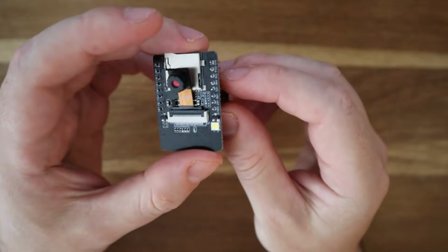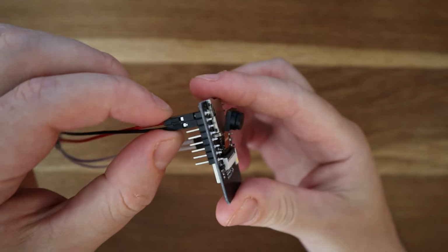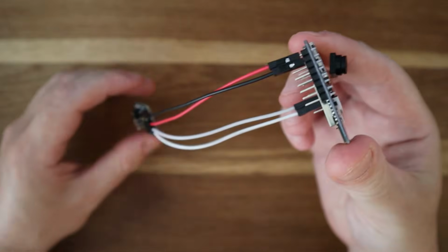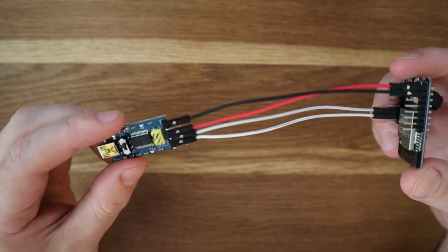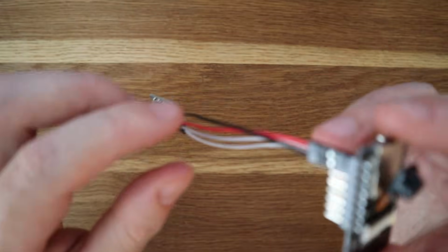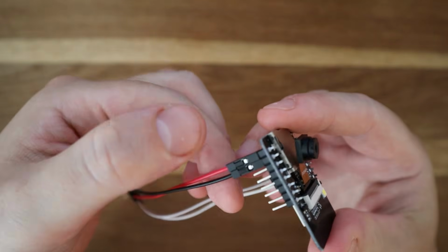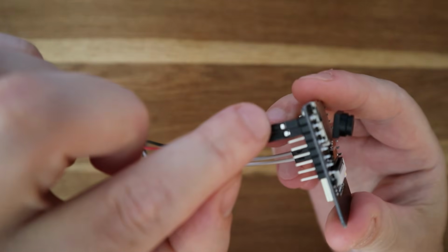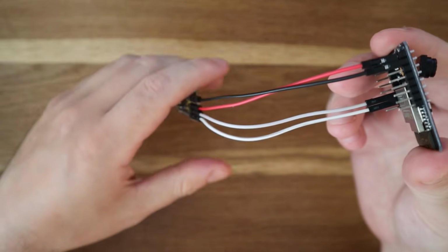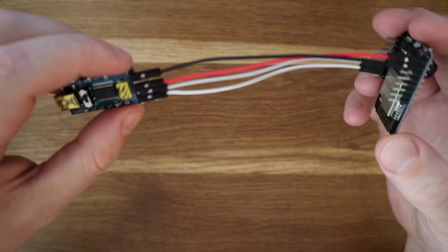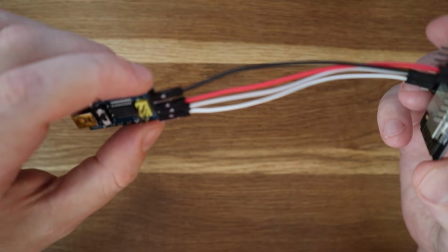Okay, so remember, these two are the pins we are going to use for the data transmission, and then these two pins over here are the power supply, and everything is okay. Please make sure you don't make a mistake, most importantly with these two pins over here, which are the power supply, because if you make a mistake and you switch them around, if you connect the ground in 5 volts and 5 volts in ground, then you are just going to destroy the device. So please make sure everything is properly connected and you don't make any mistake.